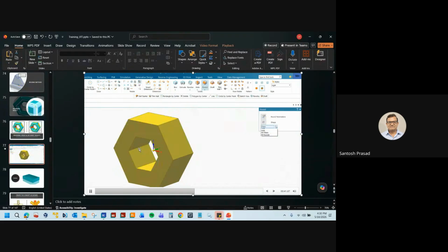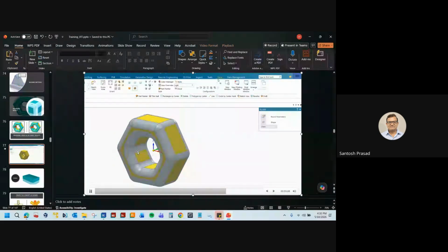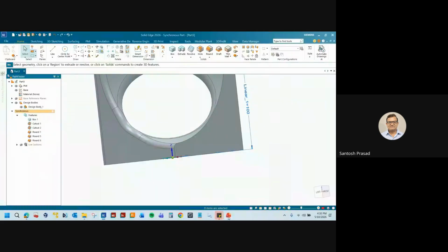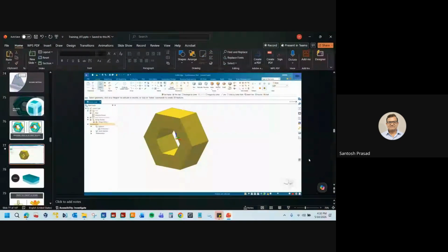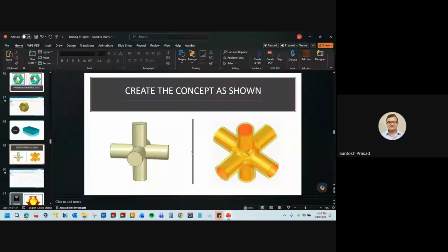For forging or casting, that is not good. So what happened is, now the blend has been created in one go, and now you can see the flow of the blend. This is how we can approach this. So this is also important, in which sequence you select the edges to create the blend, and the blend will be created properly.